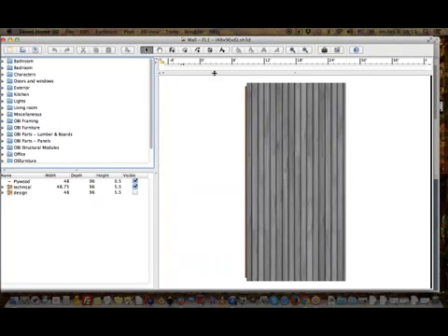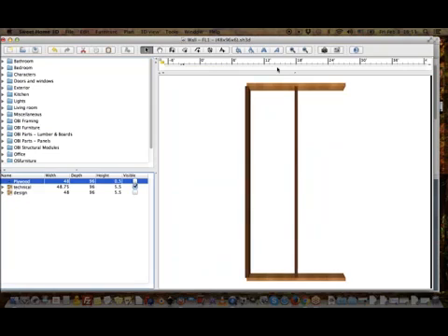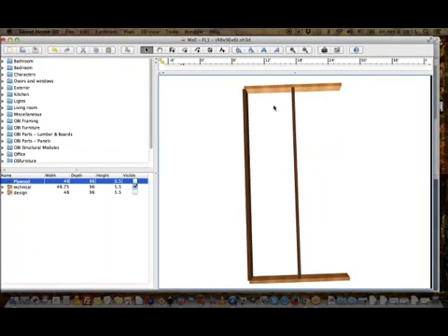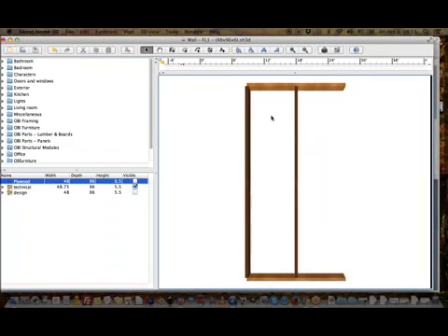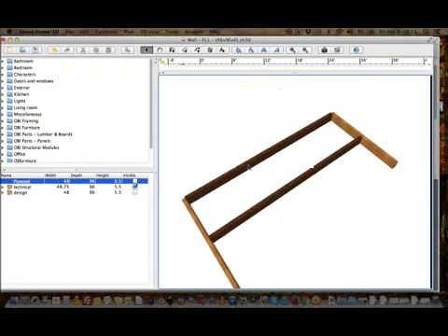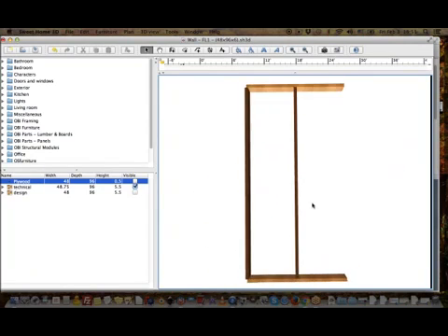Okay, so this is one of the modules. I'm going to remove the panel so you can see the inside. And this is what our modules that we used recently look like. So you have a top plate, a bottom plate, a stud in the middle, 24 inches on center, and then you have another stud that is offset. You can see here that this stud sticks out 3/4 inch. And the reason is that when I have a second module that looks exactly like this one here on the left, they're going to interlock, they're going to fit, right? It's basically the Lego principle.